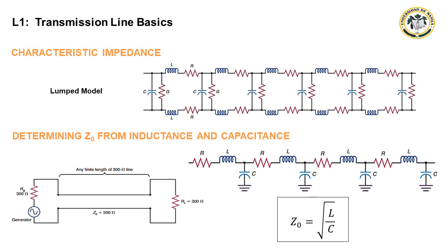Assume that a capacitance of 0.0022 microfarad or 2200 picofarad is measured for 100 feet of transmission line. The inductance of each conductor is measured separately and then added for a total of 5.5 microhenry. And let's assume that resistance is ignored because it does not enter into the calculation of characteristic impedance.